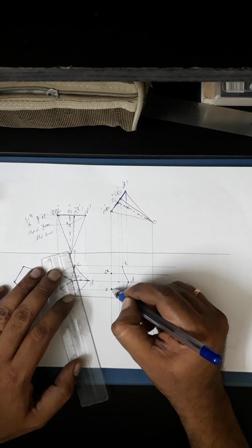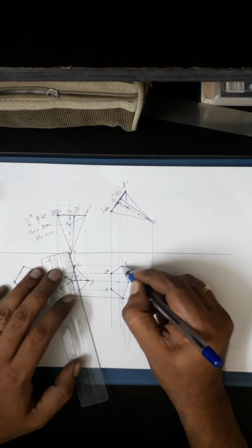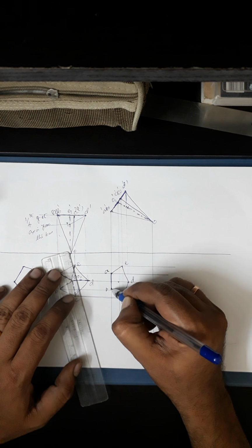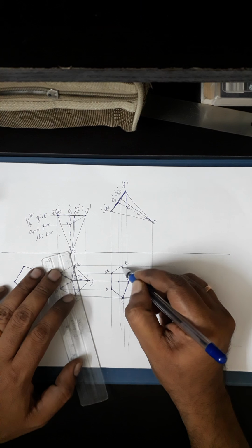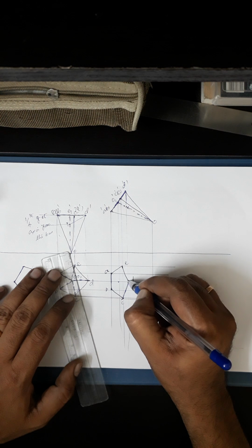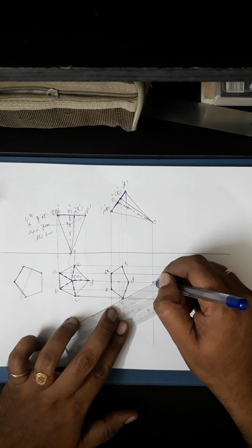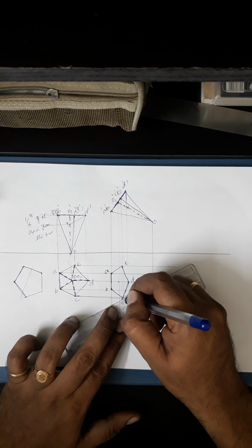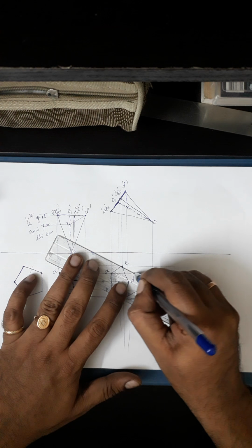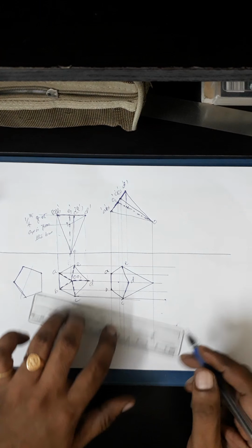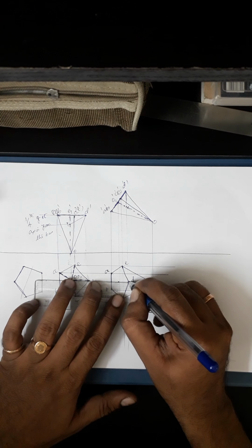will be a true inclination. Since the axis will become apparent here, the inclination with VP, I told you that in these suspended problems, only the axis inclination will be given only with the VP. So if you don't find those three sentences along with that inclination in the exam, in the question, then you have to go for finding the beta angle. So this is simply something like this.